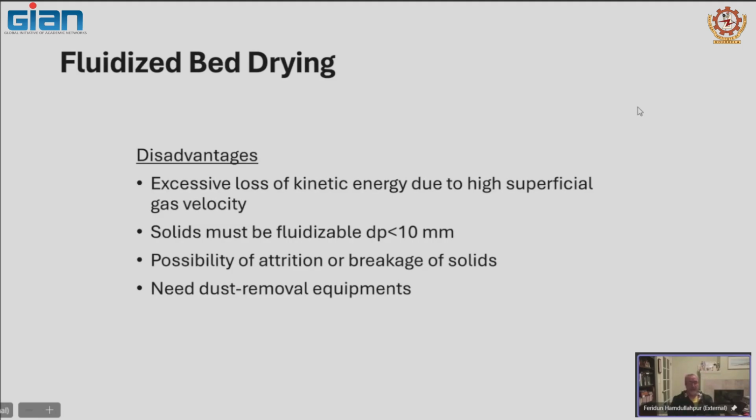as again, we are putting a lot of air through here, and you can easily calculate the amount of energy you need to heat this air to, let's say, 60 Celsius, 65 Celsius, and you're putting through, I don't know, at least a few tons of air per hour. So it costs you money, but then you throw this air out at the exit because you need to continuously provide air. So it's a continuous process, whether it's batch or not, but still air must be moved.